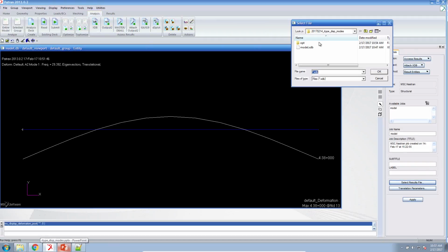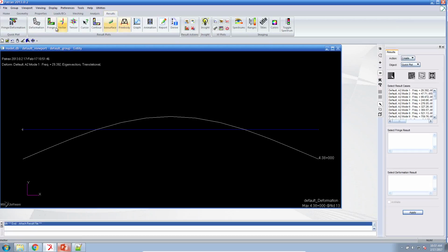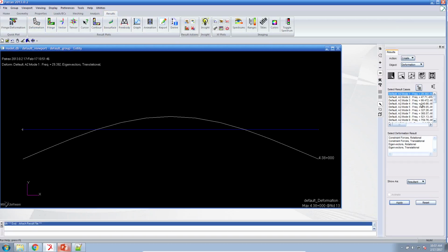The result file that was created during the optimization process includes both the results of the original design. So here this will give us a 4.38 or negative 4.38. It gives us the initial results, and if you scroll down, we have another set of results. And you'll see, if it says D0, so D as in Delaware, that means it's design cycle 0 or the initial analysis.